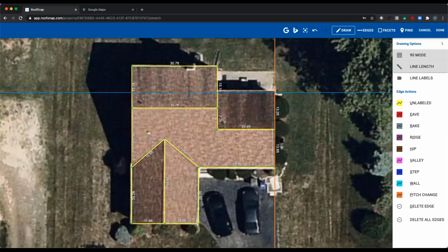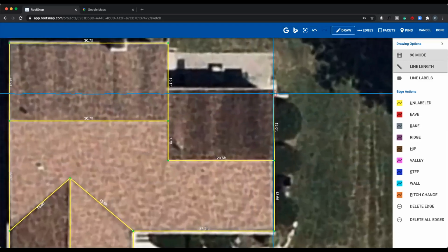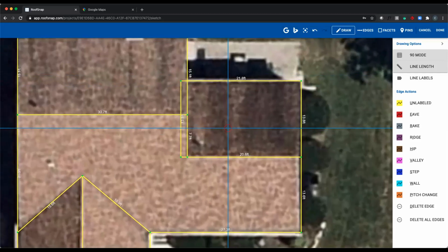And we're essentially, by drawing it underneath this facet over top, getting that extra surface area of that overhang. So started our rake. Let me zoom in a little bit so you can see this here. Left click, this eave, I'm going to draw it over just past that rake that we drew up ahead, taking our step wall line up and then connecting it into our ridge line there.